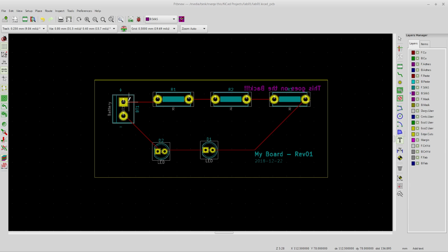And you have a thing called tolerance. In CATIA and Fusion 360 and anything in the shop that we're doing on that side of the fence, in my other videos you watch, you can't put a 10 millimeter pin in a 10 millimeter hole. It does not fit. You need a little bit of tolerance, unless you freeze it or heat something for a massive interference fit.